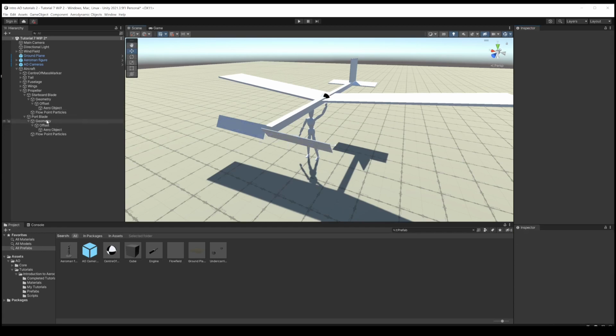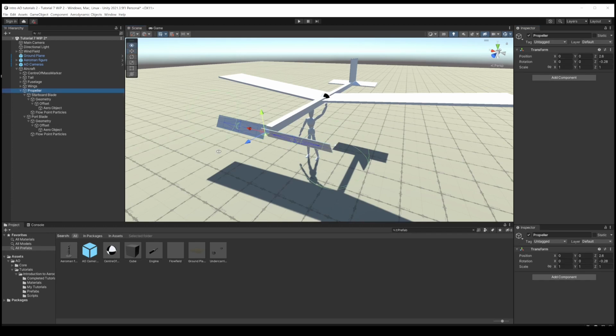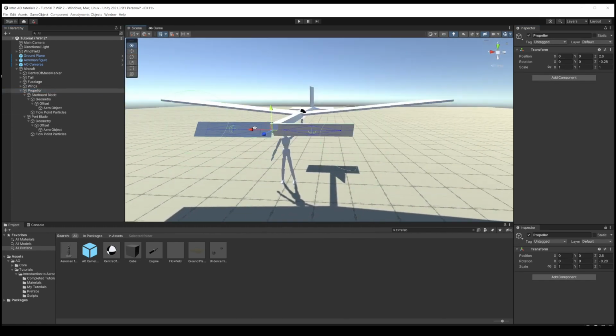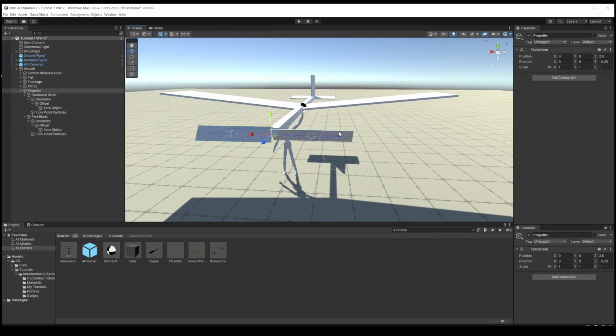The other thing we're going to do is an aerodynamic thing. If you're modeling propellers, generally if you're taking a control point on the propeller to work out the aerodynamics, you normally take 75% chord. If you imagine when the propeller is spinning around, the outer bit of the propeller is spinning much faster than the inner bit. So if you're modeling the aerodynamics of it, it's better to take the average velocity somewhere out here, and the general practice is to take it at 75%.